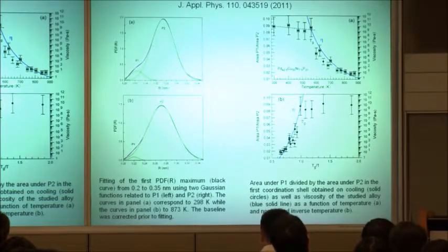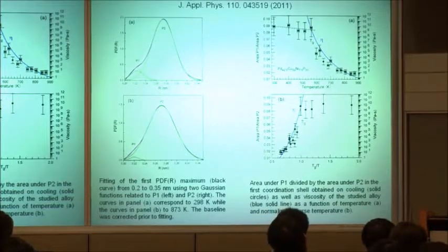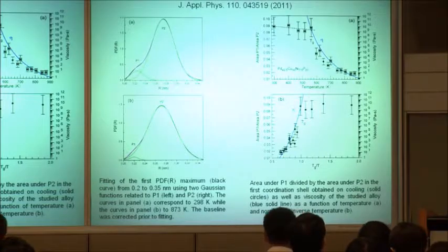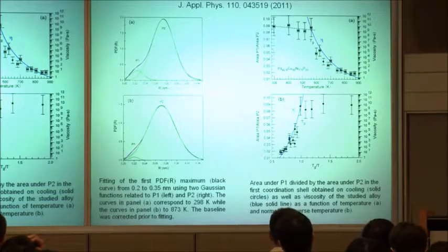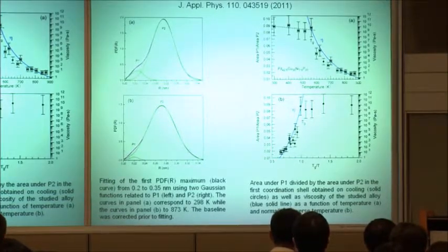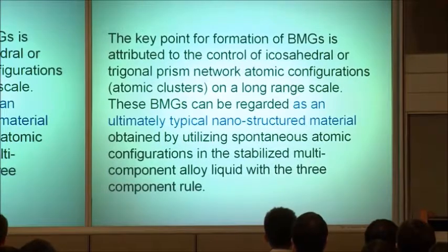The main peaks are broad at the liquidus temperature, and narrow with very high intensities at room temperature. These sub-peaks also develop at room temperature, indicating the development of short-range and medium-range ordered atomic configurations during the cooling, accompanied by a significant increase of the viscosity.